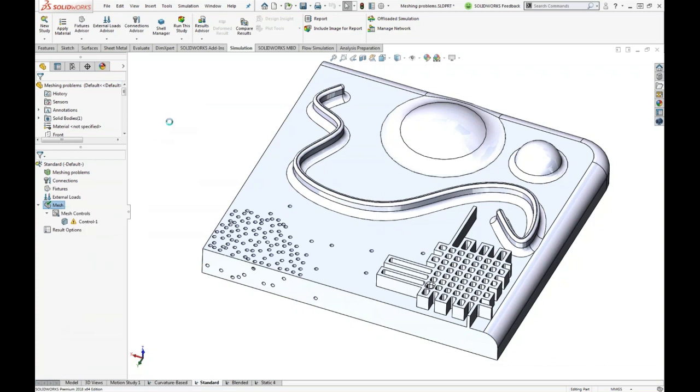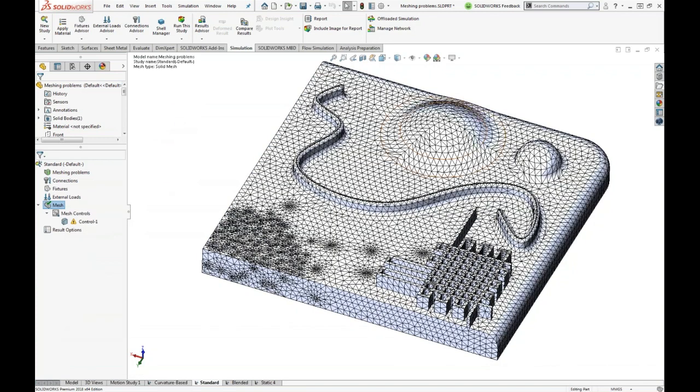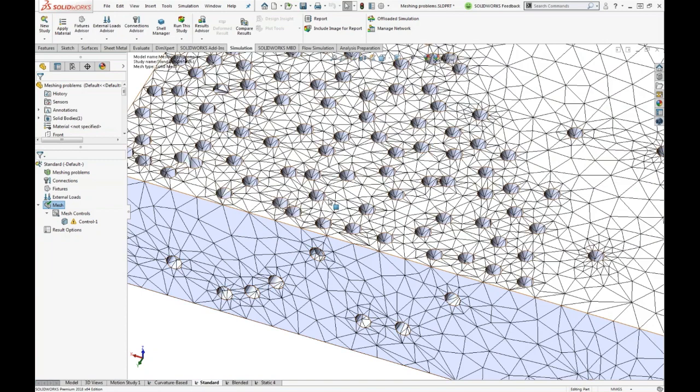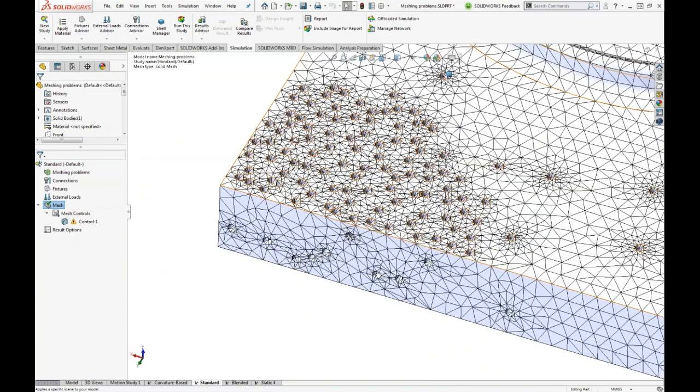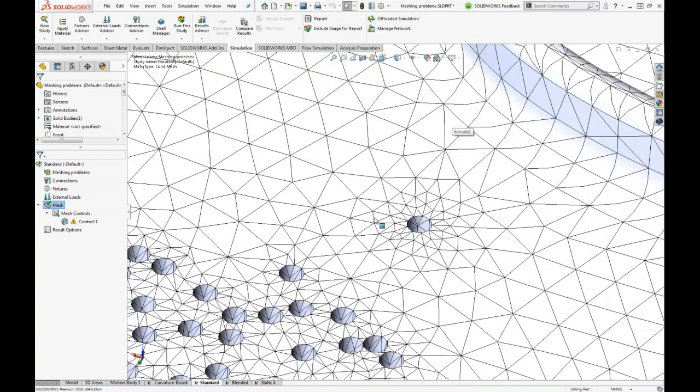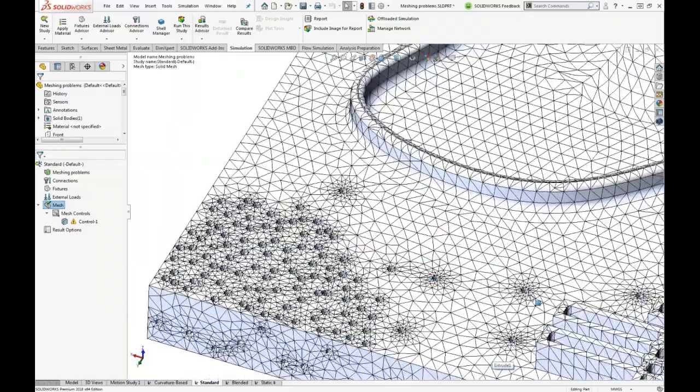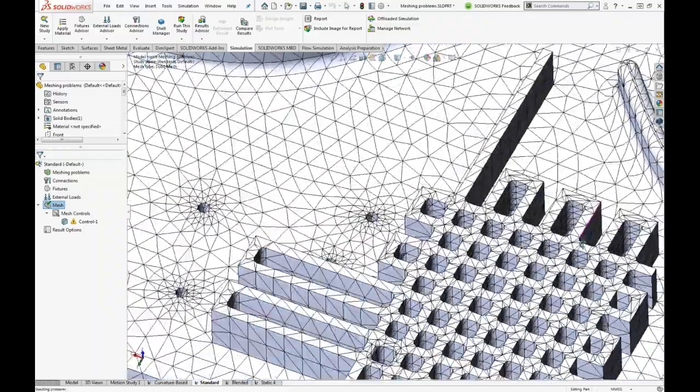I think I can show mesh. And so what you'll notice with this particular mesher is everywhere away from those controlled areas is a very regular, even size. Right? See these ordered rows, and then as we get into the areas where I had to refine, you've got a bit of a transition going on in those zones, but that's all being applied manually, essentially.